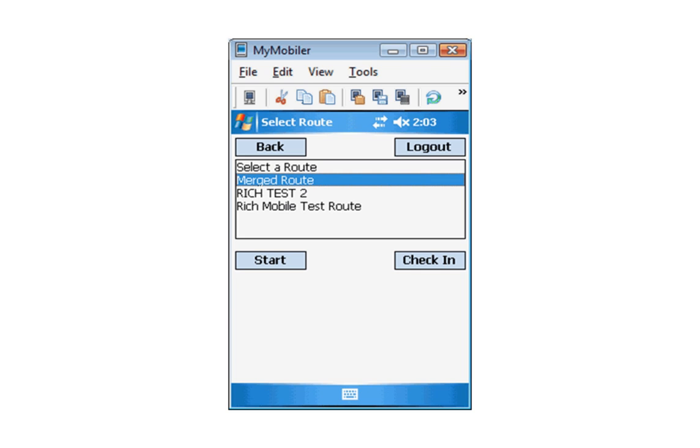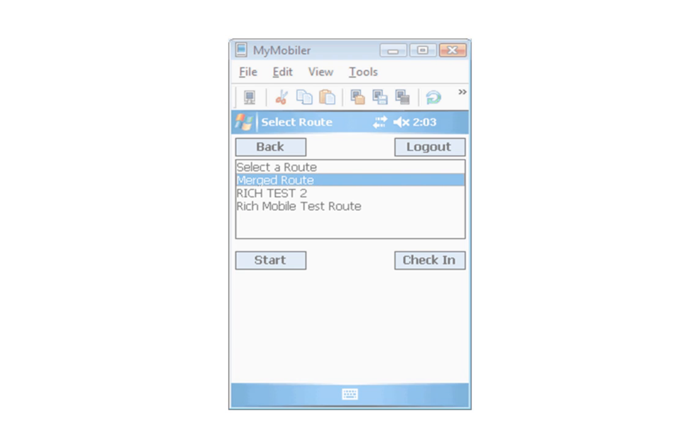However, you have also loaded a quarterly route for regreasing for the same assets X, Y, and Z. It will be cumbersome to complete these routes separately, or to have to go from one route to another to enter information against all of the data points for each asset. The Merge Route feature will combine the route lists for each route into one route list, so when you are standing at asset X, for example, you will cycle through all data points for both routes. In essence, you will be completing both routes simultaneously.